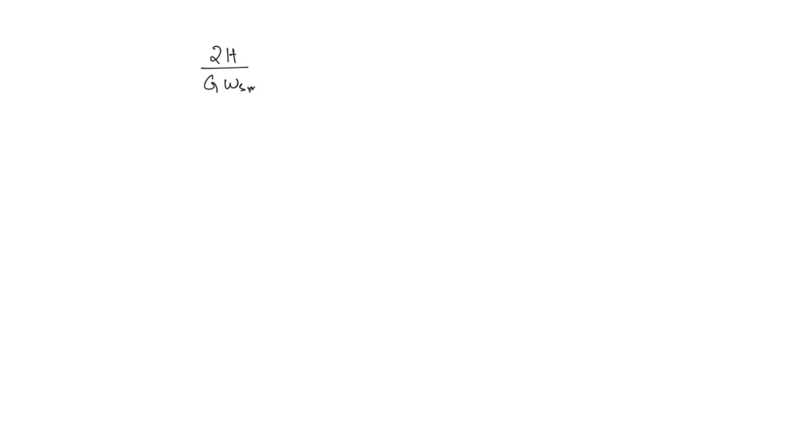This is the swing equation that we discussed before. d square delta m by dt square, this is equal to PA, which is PM minus PE. Now what is a per unit value? It is equal to the actual value divided by the base value. So this entire equation, if you divide by the base value, then you're going to get the per unit values of this power, right?